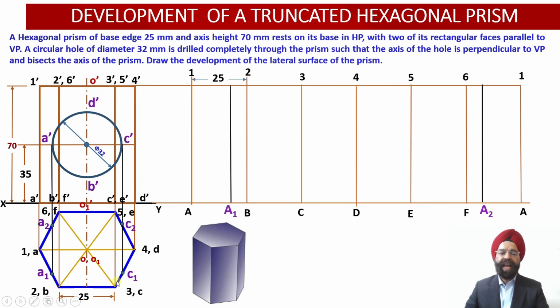So now we can check as we move along edge CD at this distance between C and C1 alongside the edge CD, we'll be able to obtain point C1 over here. So we can check alongside the edge CD at a shorter distance from the point C, which is equal to this distance, we are able to locate point C1. So once we draw another black color artificial vertical generator through this point C1, onto this vertical generator, we are going to obtain location of the point C corresponding to the front face circular hole over here.